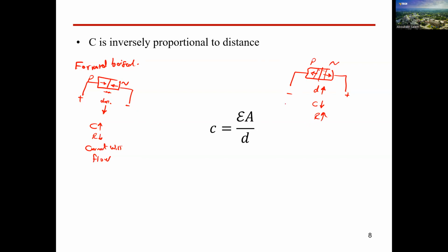If you would like to know some numbers, guys, semiconductor materials can have resistances in milliohms. We have some semiconductor materials now where the equivalent resistance of the PN junction can reach 0.1 milliohm, a very small value of resistance. And here, in case of the reverse bias, the resistance can go to hundreds of megaohm or gigaohm. So it's like complete isolation, which means in forward bias a high current can flow, I will be flowing with high value, but here the current is going to be only I leakage. The leakage current, which is the saturation current, is in picoampere or nanoampere, a very small value of current. So this is the concept of forward biasing and reverse biasing that we discussed in the last class.